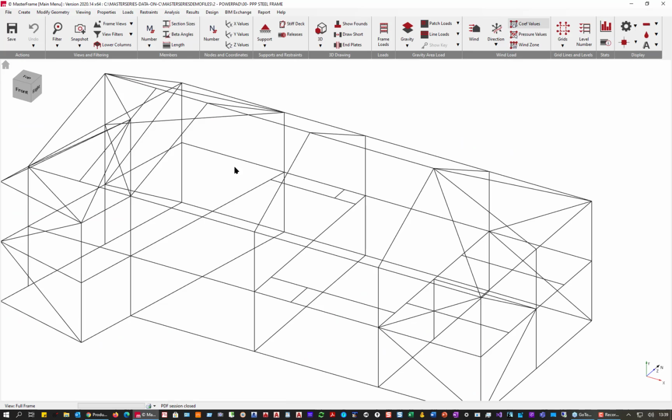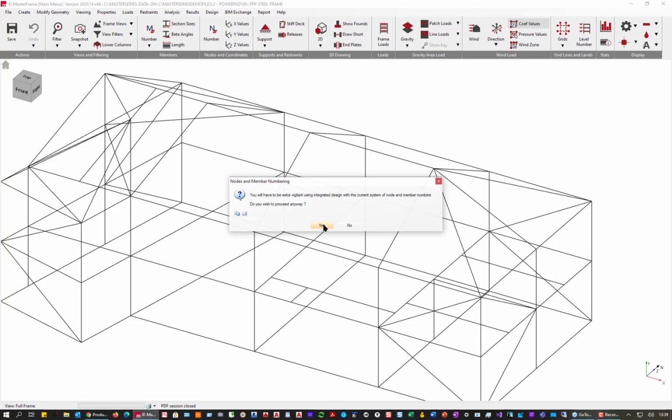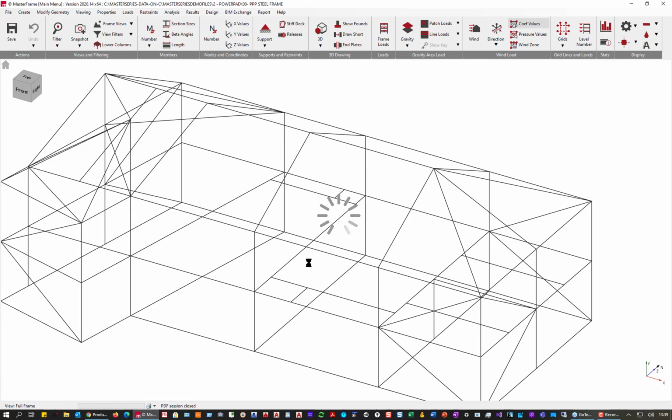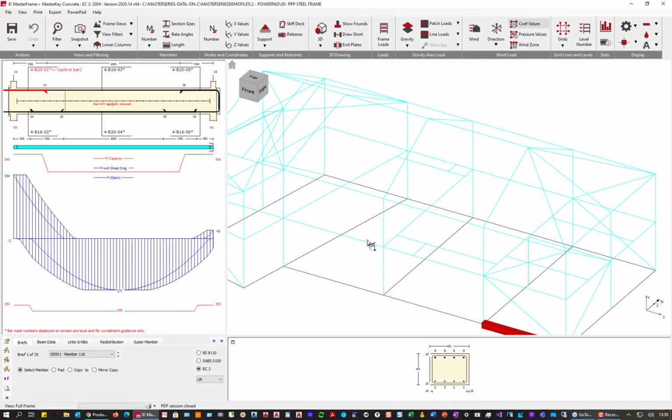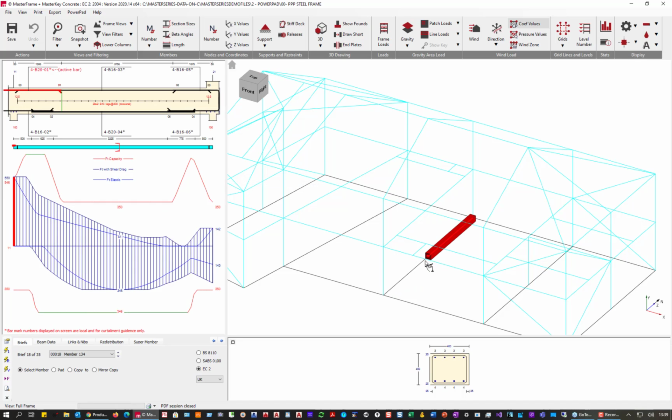We also had concrete beams. So let's just go straight in and do our concrete beams. And it's just warning about the direction of that one member, which is not a problem. And if I look at any of these beams, it's got a little failure here and here because we have a pile under the middle of this to separate the span out, because it's all on piles. Otherwise, why would you have ground beams? So it's all on piles. So these need to be sorted.